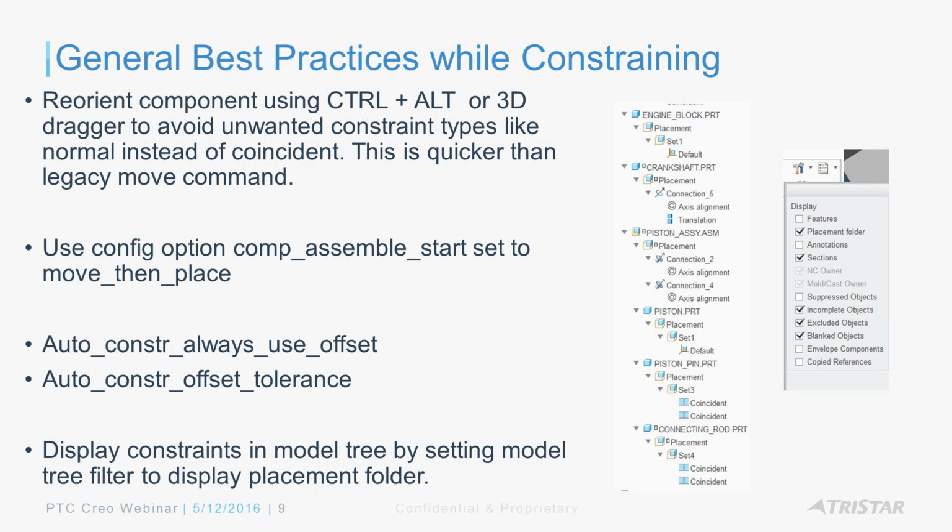As you know, in Creo, every component has a model size, right? If you go to your information tools and check the model size, it's the largest diagonal size of the box that encloses the part, roughly. So it uses that, and depending on whether it's less than that or more than that, that's when you see how sometimes it snaps to be coincident, or sometimes there's an offset there.